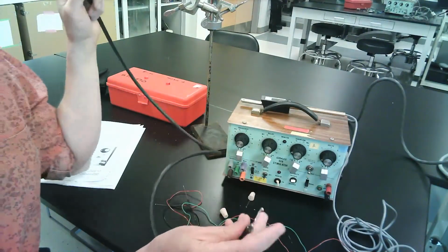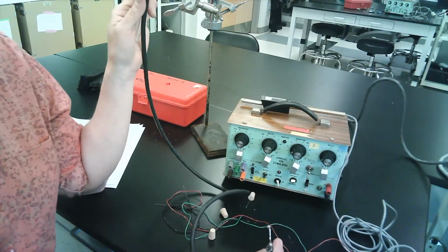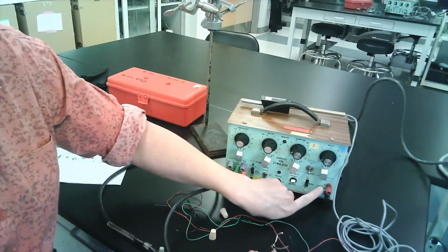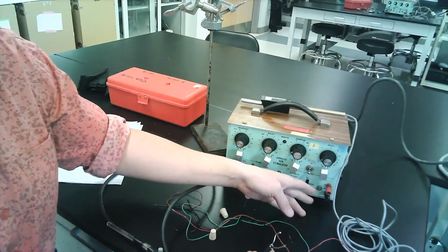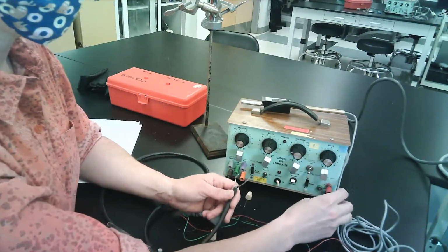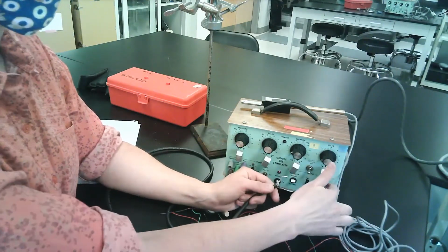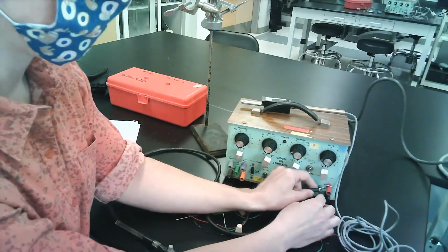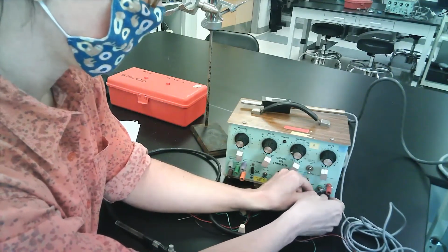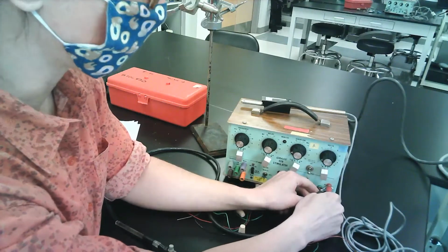So for delivering our stimuli, you're going to use a stimulator that looks something like this. And it may have either 2 or 3 wires coming out of it, so you're going to have a positive, negative, and potentially also a ground. This particular stimulator suffered some abuse 2 years ago, so the ground connection is missing. And there's actually a couple different ways that we can plug into the stimulus. And in this case, what we're going to do is these knobs will unscrew. They'll expose a metal section, so we're just going to contact metal to metal to connect everything up. So I'm going to lay that in, then I'm going to tighten this down to hold things in place for both the positive and the negative. In this case, I don't need a ground necessarily.